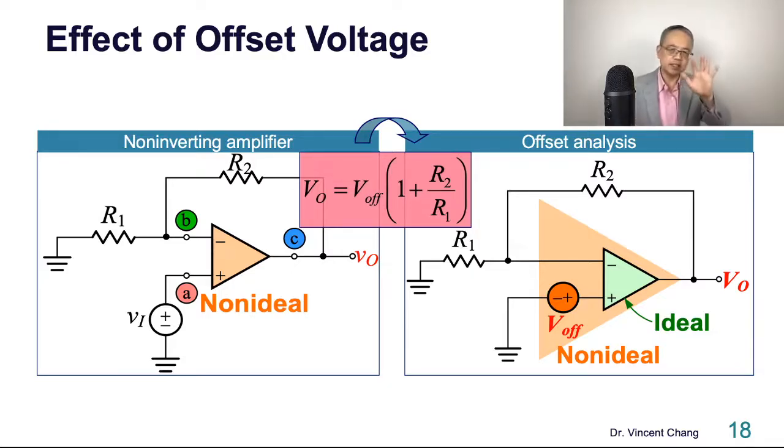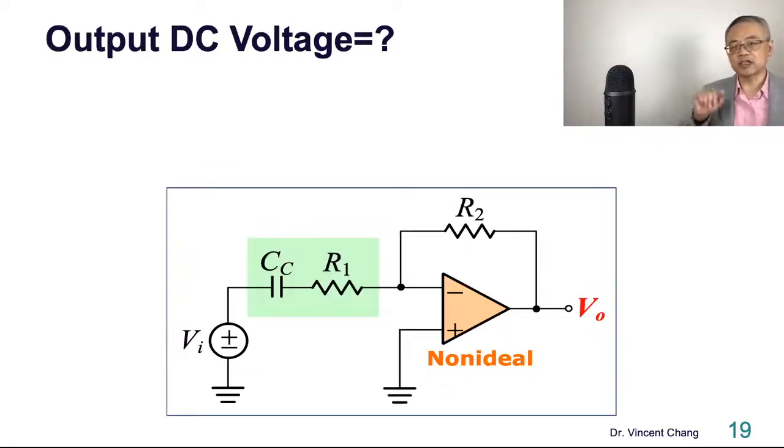So is this good news or bad news? Of course, it's bad news. Why? Because you expect the DC to be 0. So then you can have this kind of swing. And in the previous series, I was talking about the ceiling voltage, right? So you're going to hit the ceiling, right? And then sometimes even cause distortion. So if you don't want to suffer distortion of your output signal, then you have to limit your swing. So your output signal swing is limited. So this is not good news.